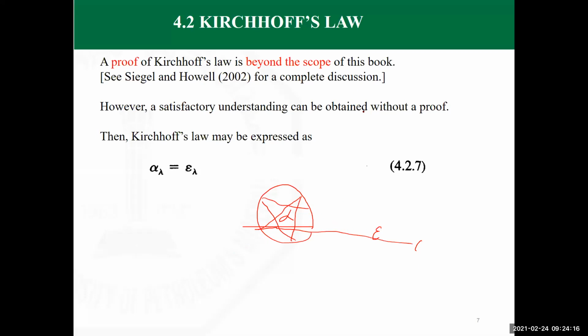Another thought experiment is given in your book, saying that if you have a cavity with two surfaces of different radiation characteristics, and it's all in thermal equilibrium, it means that eventually, since we're talking about equilibrium, the value of alpha absorbed by the surface is going to be in balance with the value of epsilon, the emissivity, so that it remains at a constant equilibrium temperature.